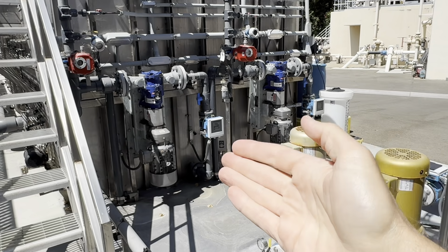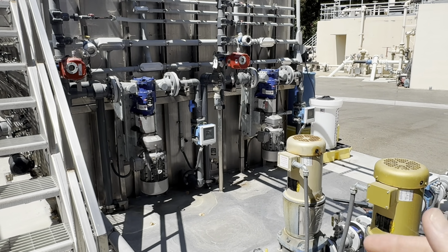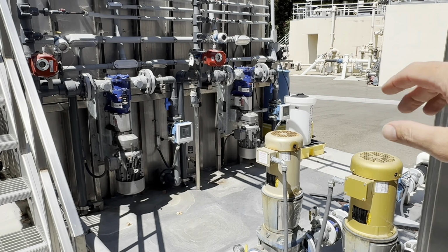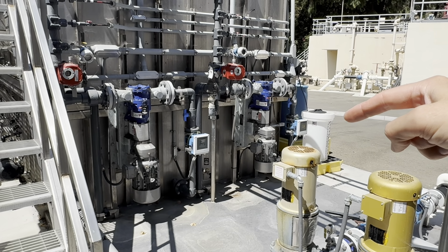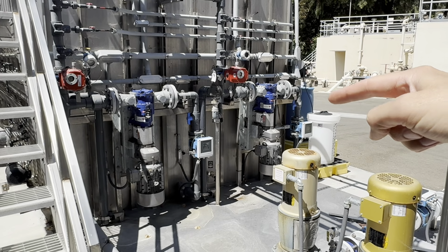Okay, and over here we have our permeate pumps. They're pulling that water off. Again, this is a membrane bioreactor. It's a little different than conventional, but it's worth showing you. These are our effluent pumps that are pumping off. And then over here you'll see a couple chemical tanks. That's a sodium hypochlorite for our clean in place. And our citric is the blue for our clean in place as well.